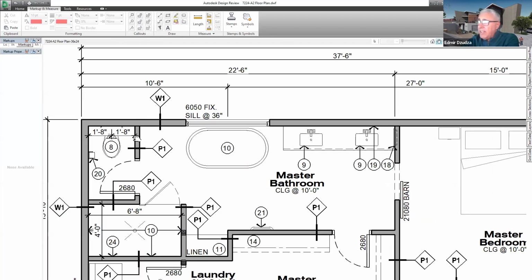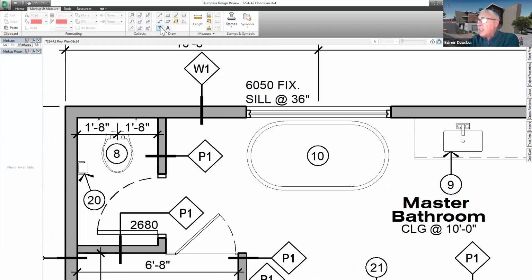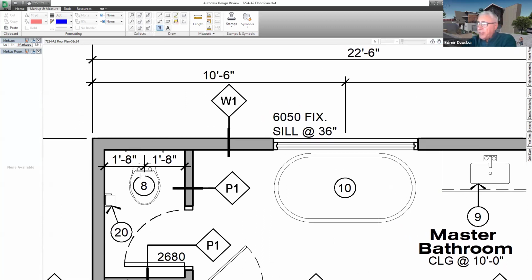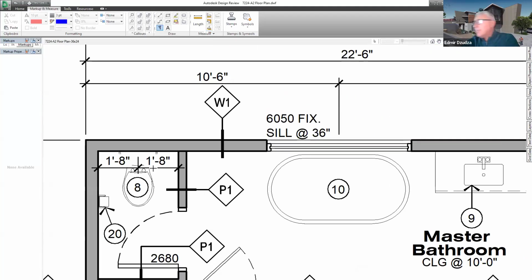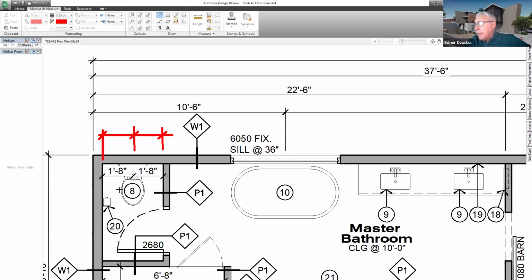Now, I don't know, let's say this wall here. We don't know this dimension. Yes, this dimension here is more for plan review purposes. But when we're dimensioning, we need to try not to cover the drawing. So what I would recommend is to pull these dimensions out, so this block stays clean of any dimension, clearly showing a toilet.